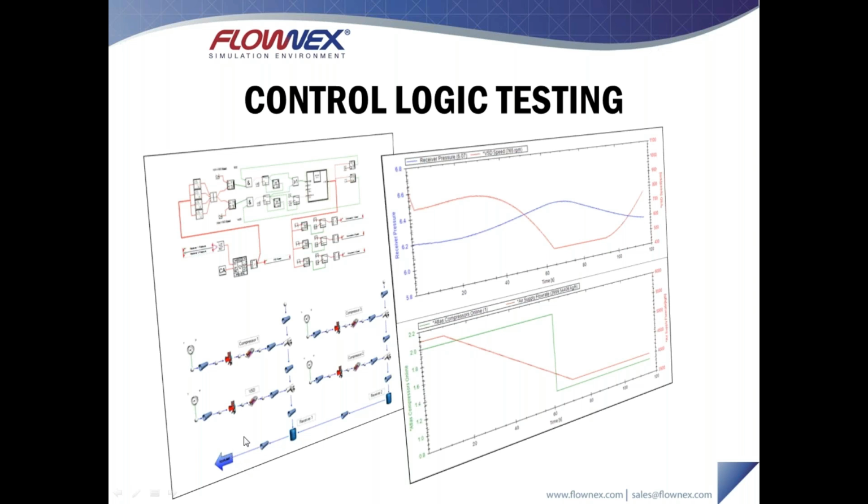So the actual air supply from here changes, and as a result, the number of baseload compressors online needs to change. To make up the deficit between the on and off values of the baseload compressors, we then have this variable speed compressor. The variable speed compressor is controlled by the PID, and this PID simply adjusts the speed of this compressor until the pressures inside of the receiving tanks are equal to the actual supply pressure that's desired. So with the speed of the VSD, with this variable speed drive compressor rather, we're then able to decide whether or not we need to turn baseload compressors on or off.